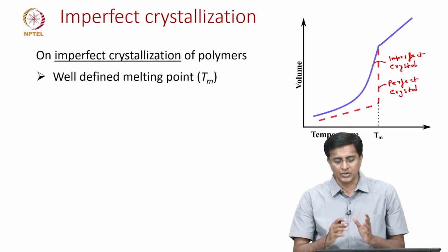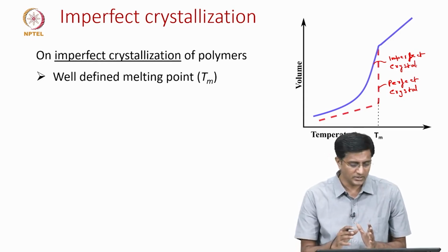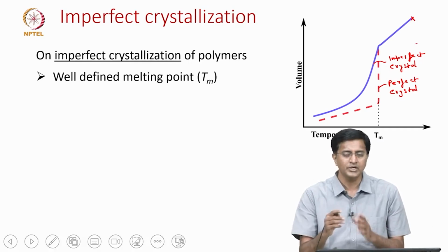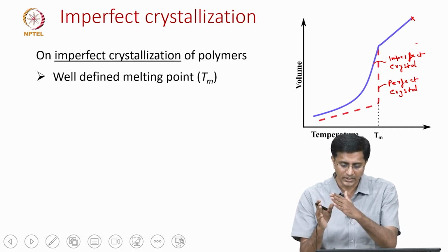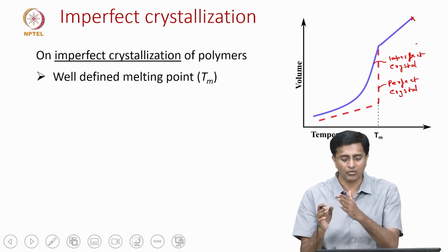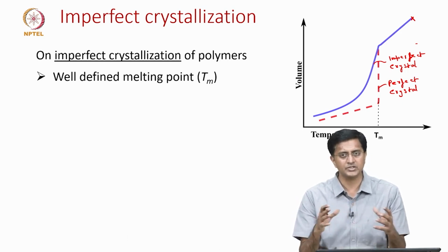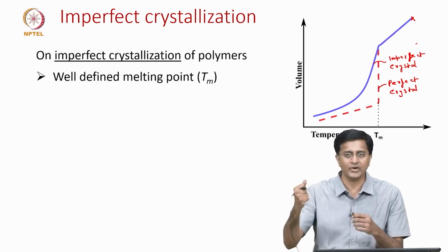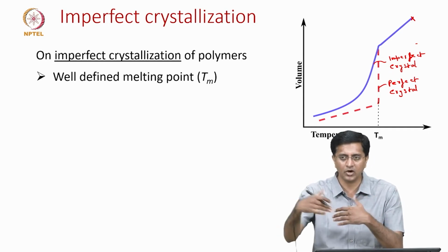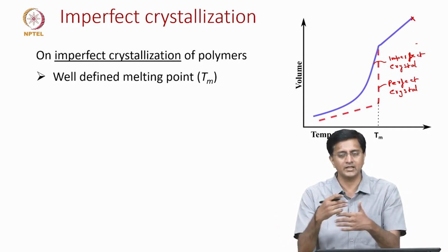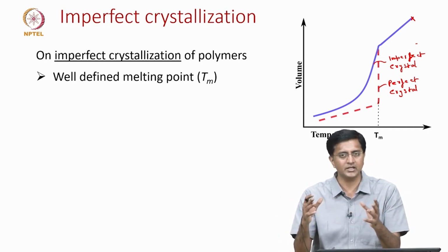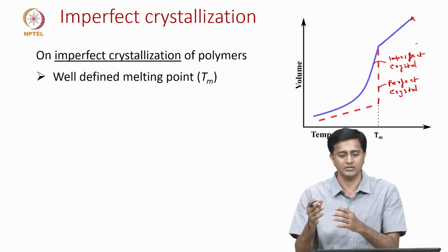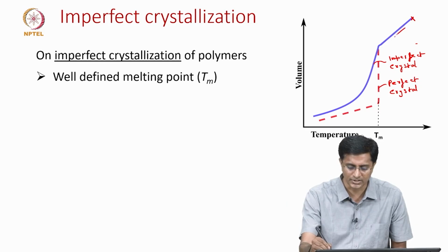Here too, we notice that when we start from high temperatures and start to cool, initially we see a linear region where the volume decreases with temperature, because, as we have seen previously, of the jiggling of atoms, and these chains are flowing past each other because at very high temperature they are mobile. We are talking about this region.